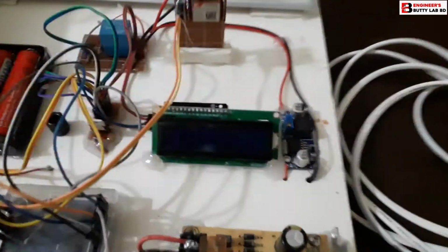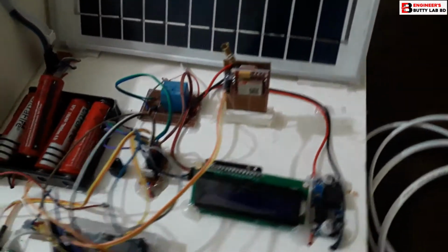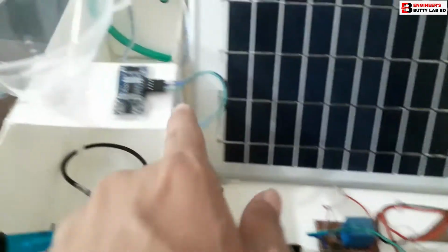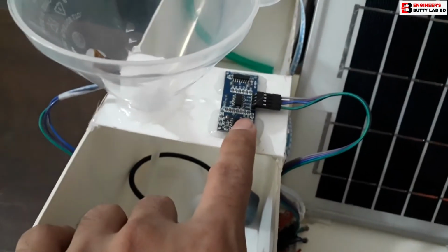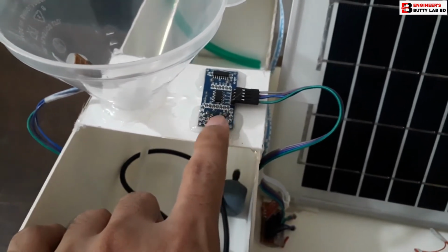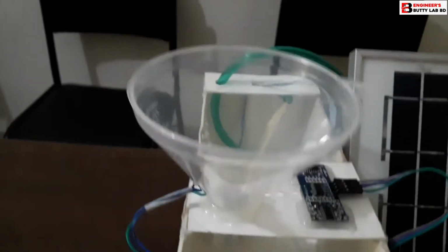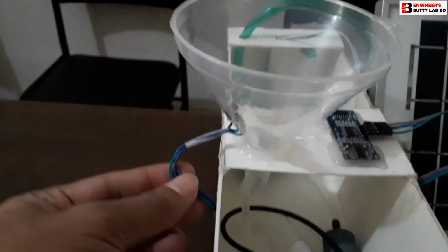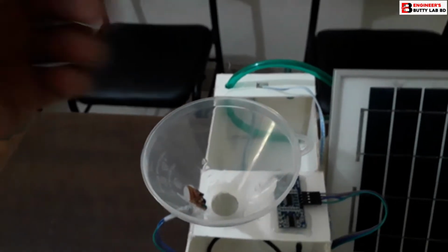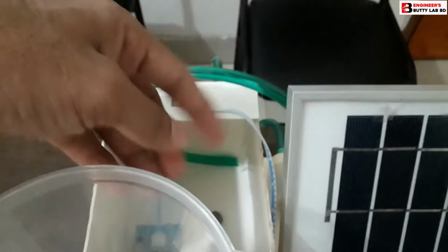And on the right side we use a buck converter to make sure the power supply for our GSM module, because our GSM module works on 3.3 volt to 4.4 volt. We use an ultrasonic sensor to measure the water level of our piscicultural pond, and we make sure here a feeding system for our fishes, and we can control the system by using an LDR. When we provide food here, at that time it will notify us that feed is available.